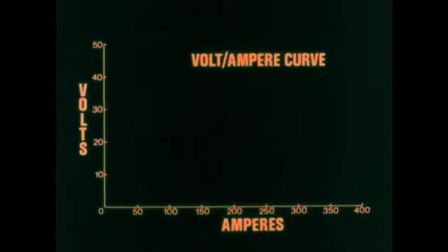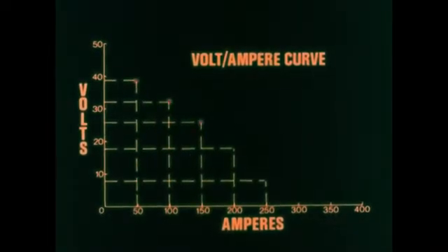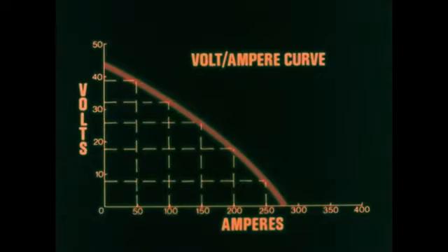The volt-ampere curve is merely a method used by welding power source manufacturers to illustrate on a graph the electrical energy output in volts and amperes of a welding power source. The volt and ampere output values of the power source form points on the graph. When a line is drawn through these points, the output curve is formed. The voltage indicated and its correlation or joining with an amperage value simply states that the power source is capable of providing that amount of voltage at the indicated amount of amperage.